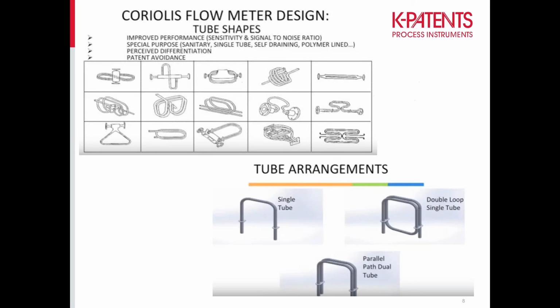Now, manufacturers commonly use Coriolis mass flow, and why is that? It's because multiple measurements can be made. It's almost like a Swiss Army knife in the instrumentation world. The primary measured variables, mass flow, density, and temperature, can be used to derive any other variables such as volume flow or total solids or concentration. So like a Swiss Army knife, there are many things that can be arrived at from the same device.